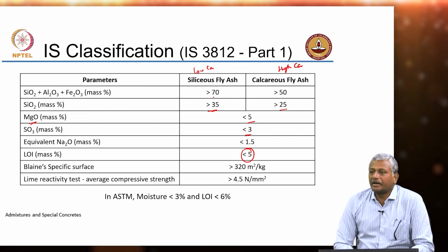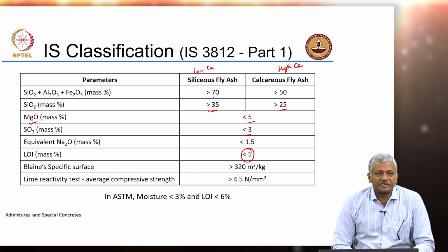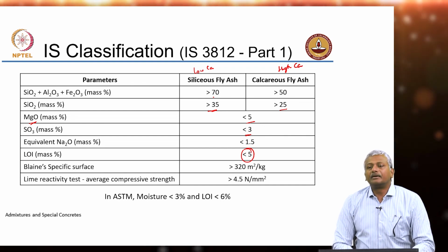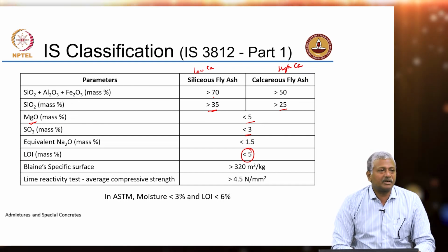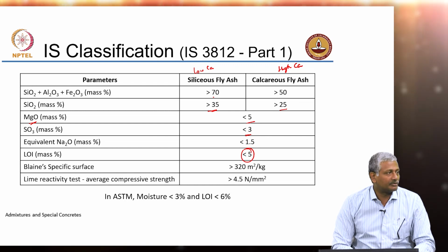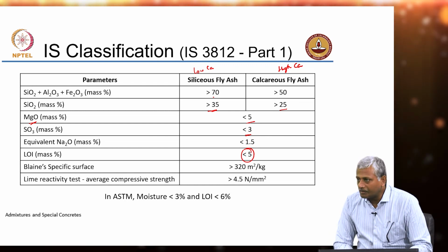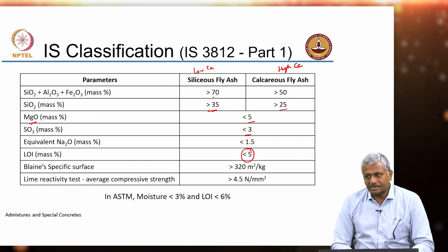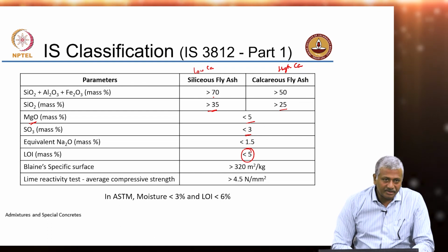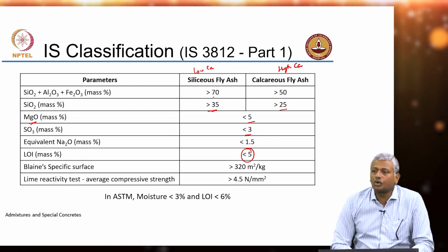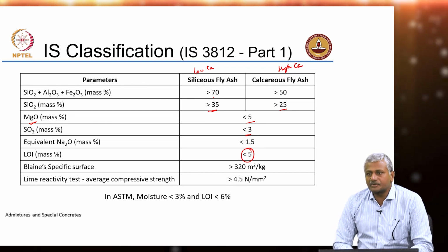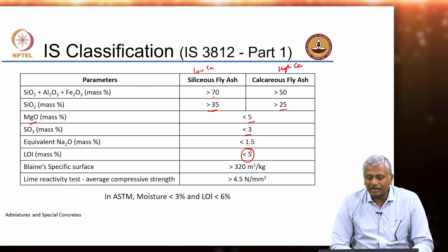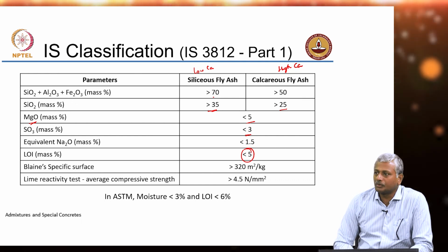There may be organic matter, carbon bearing matter that is present in the fly ash, because it is from coal, there will be carbon definitely, and if it is present in excess quantities, it is going to interfere with your performance, primarily with respect to air entrainment. It may also affect your effectiveness of the superplasticizer. It may affect the overall strength gain characteristics and so on. So, we do not want too much carbon in the system. As far as possible, carbon has to be removed from your system. So, how do you remove this carbon? If it is in excess of 5%, what will you do?